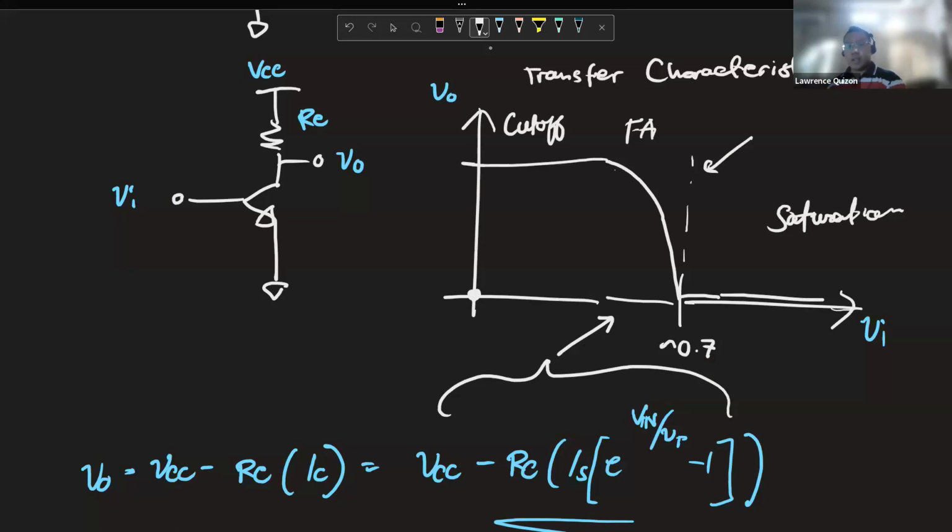All right. So, now, in terms of quiescent point considerations, again, this A, this is B. If I told you guys to design something with a high gain, a common emitter with a high gain, which quiescent point would you choose, A or B?